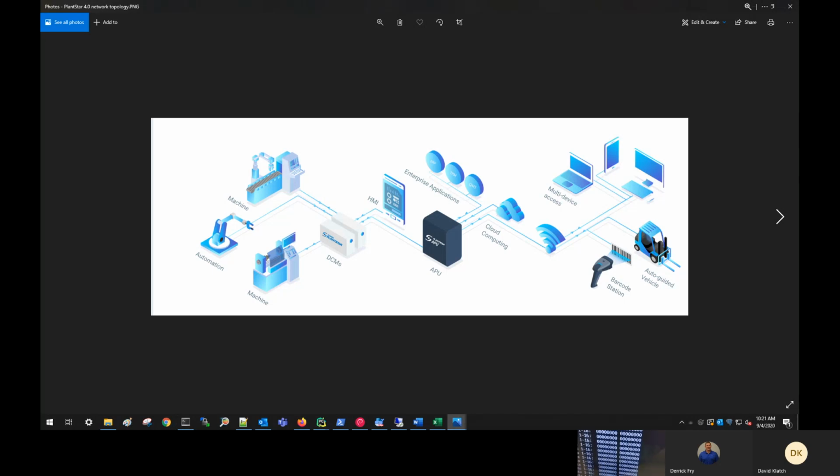It'll show you what digital information is coming in. So Vincent, the green things you were showing, that's where a copper wire would go from the machine into each of those pins, and the thing on the screen is every column represents one of those inputs. If a signal comes in over the wire, like if these two are shorted, then it'll show as a 1.